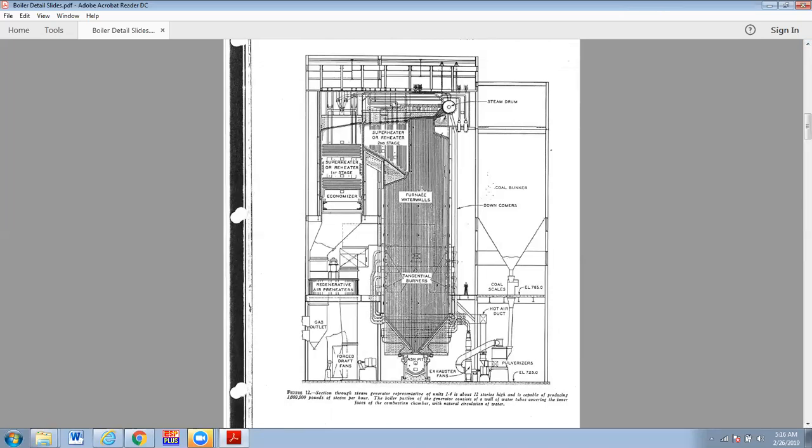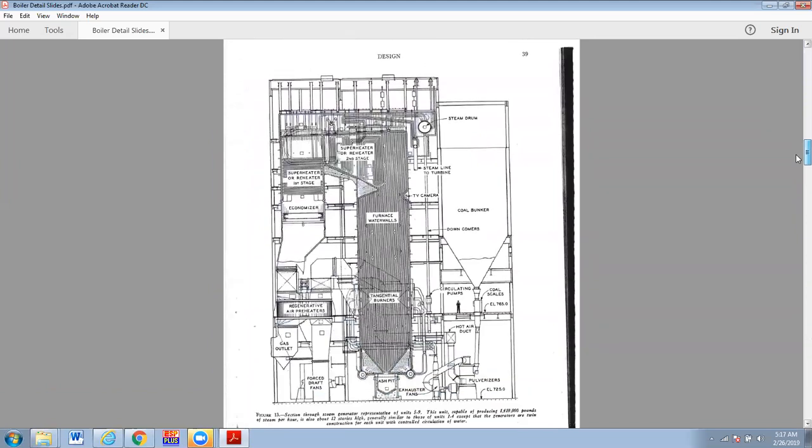So you can't just constrain all of this, because when you heat up that metal, it's going to expand, and they're tall enough that you get a significant amount of expansion. If you constrained it on both ends, when it got hot it would simply buckle the tubes, or it would rip something loose. Whatever the weakest link in the system is would go. So all of these utility boilers are suspended from the ceiling so that they can allow for the thermal expansion to take place. Let's go down and see what else we got here.